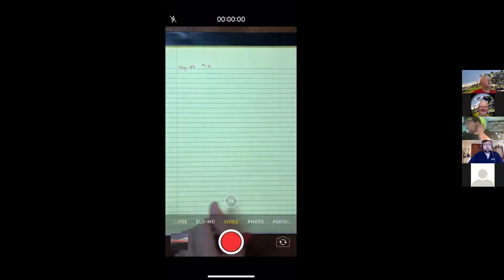All right, so it says here, an inductor, 400 millihenries, and a capacitor, 4.43 microfarads, and a resistor, 500 ohms, are connected in series. A 50 hertz AC source produces a peak current of 250 milliamps in the circuit. Calculate the required peak voltage.